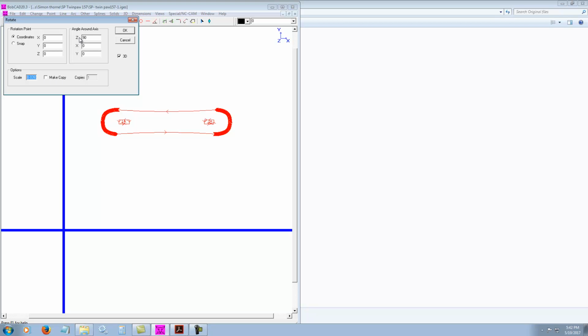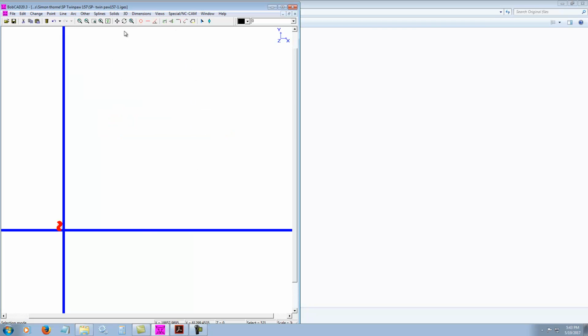And then I want to rotate this file around the z-axis, so it's going to pivot this way around the z-axis 90 degrees, and that'll get this file oriented the way it needs to be for the CNC. If you think of the right here, this axis is the left lower corner of the table of the CNC looking down, and so we're looking at the table roughly where I'm drawing this rectangle will be where the CNC router table is. So I'm going to, first of all, rotate this.